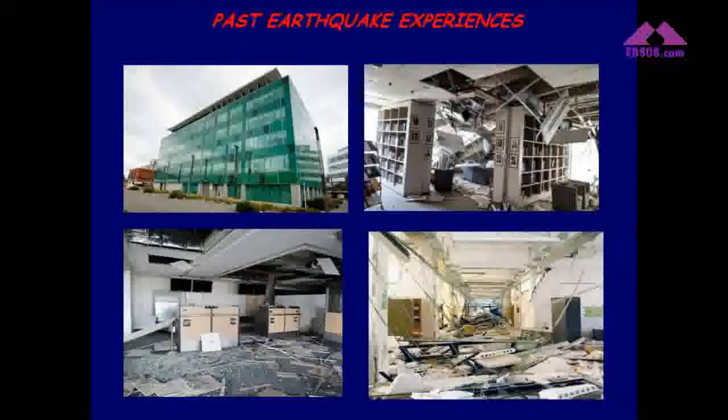For important buildings like hospitals, in the codes we have something called the building importance factor. Maybe you are familiar with that. What we do is we increase the design load 1.5 times over the general buildings. We assume that if we increase the strength like that, the building will stand still, there won't be any damage, and we will use the building afterwards. But the result is not like that. Yes, maybe your building will not get damaged after an earthquake, but when you get inside, you can see something like this image. The ceilings can fall down, the plumbing system can fail, and the building maybe won't be usable anymore after the earthquake.